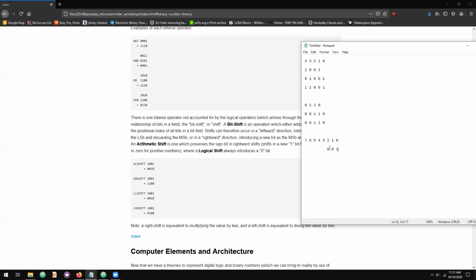If we wanted to sign extend this, it would just mean placing zeros at the rest of these positions. But if we have a value that has a 1 in the most significant bit place, if we wanted to sign extend this, you would pad it with 1s because it matches the most significant bit that we started with. So that is sign extension. Does that make sense?